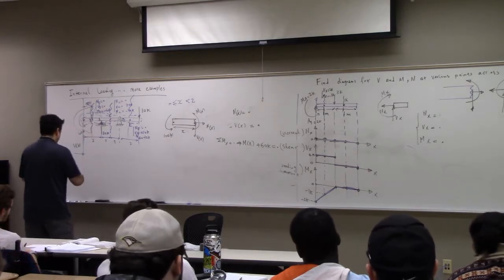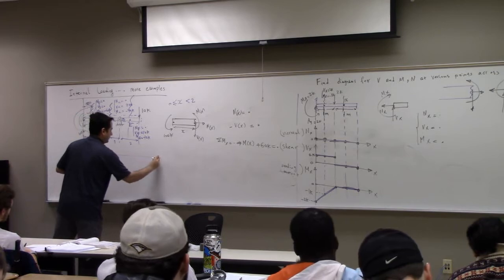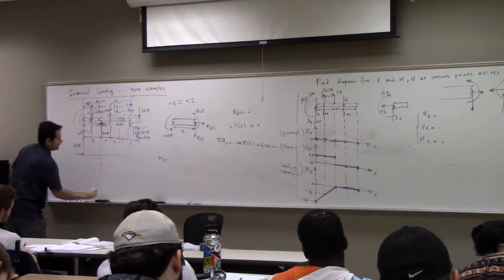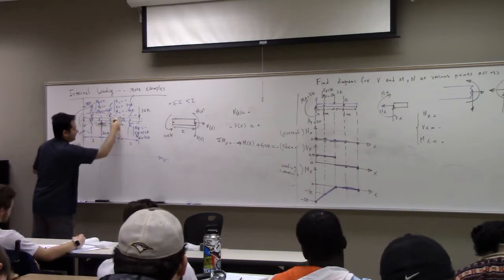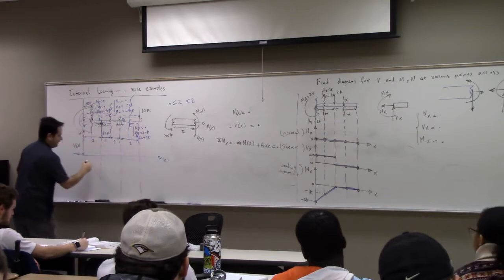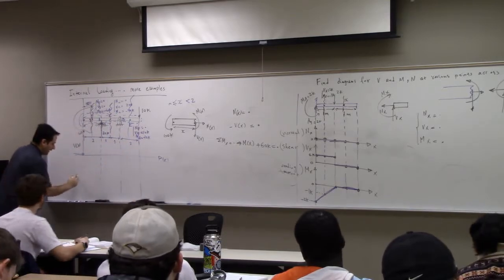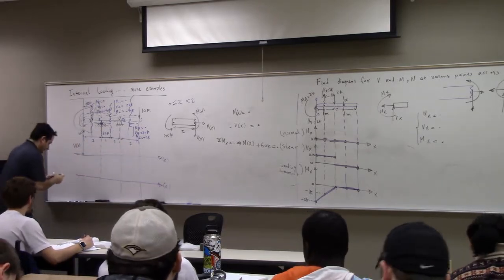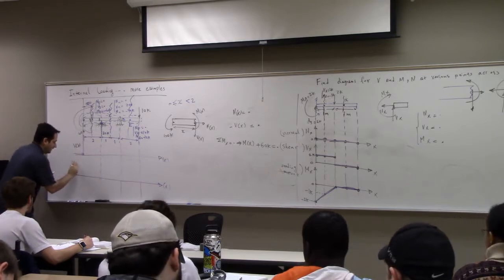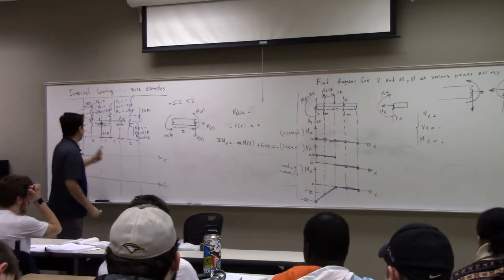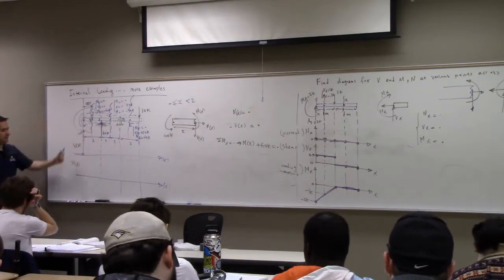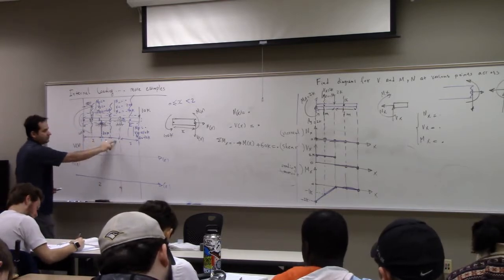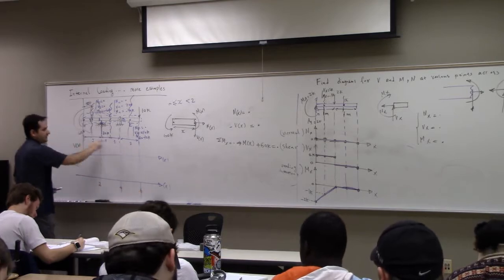And I try to make this a straight line. And this is a function of x. So for the first station, I have three different intervals: from here to here, from here to here, and from here to the end. So I have 1, 2, 3. And I have one for bending moment. As bending moment, Mx, is not necessarily 0 like Nx, this could be non-zero. So from 0 to 2, this is 2, and then this is 4, 2 plus 2, and this is 6.